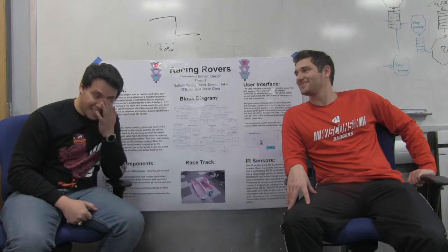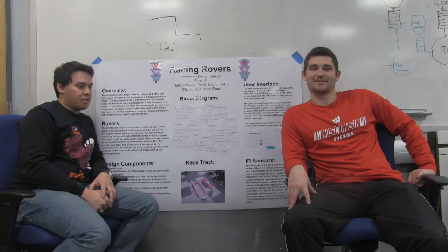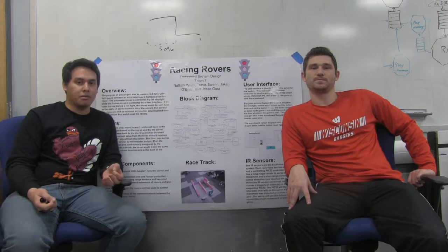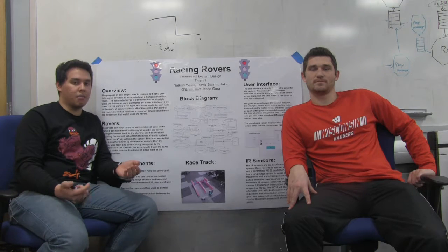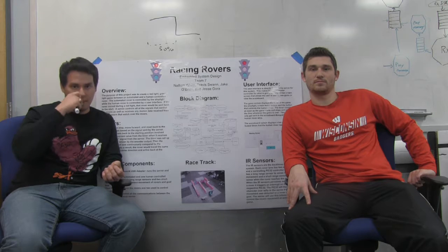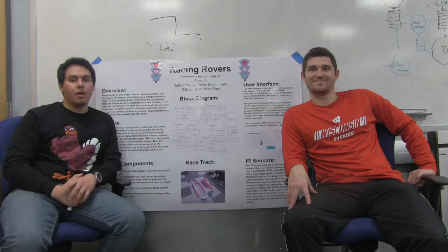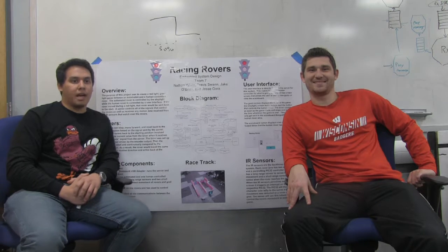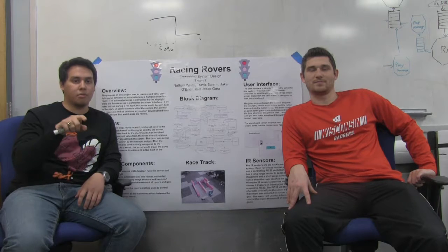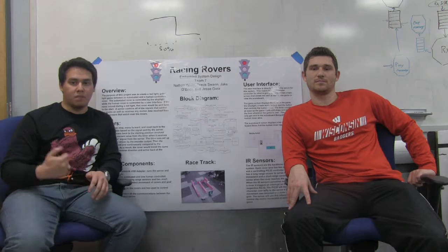After going backwards, we intended to also go back to the start. So the next step was reading the encoder values. The encoders for the motors produce a little tick every time the motors reach a certain point in the revolution. In order to do that, we had to hook up the encoder output into a timer, which acted as a counter to keep track of the ticks.